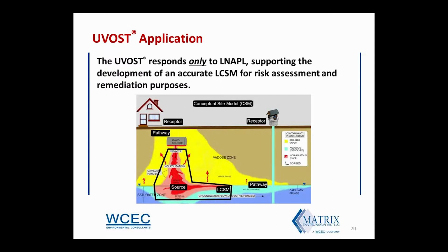But we've got some good news for you here. The UVOST responds only to LNAPL. That allows us to map out the LNAPL body for development of a reliable LNAPL conceptual site model, which is essential when performing our risk assessments and remediation.